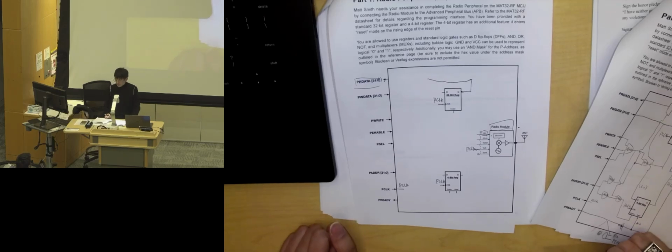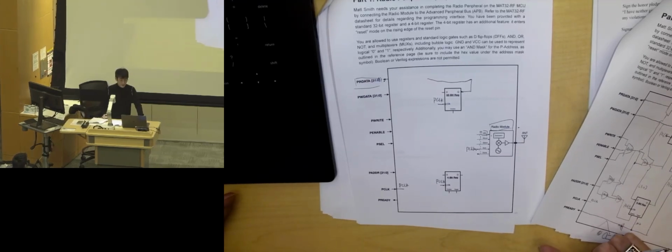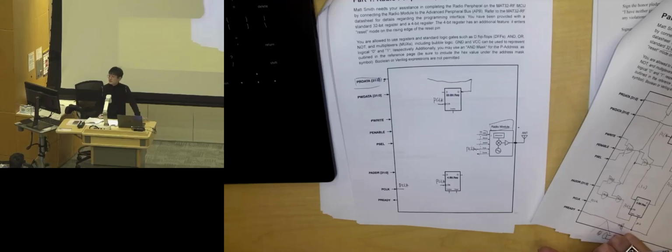If you go back and look at that data sheet, we need a register that's 32 bits that is labeled read write. We can have a register that's just write or just read, but that one's read write. Yep. So we need a read data.